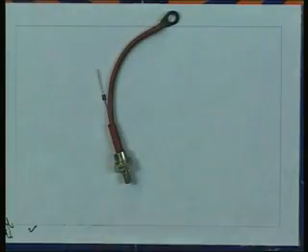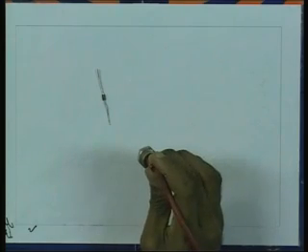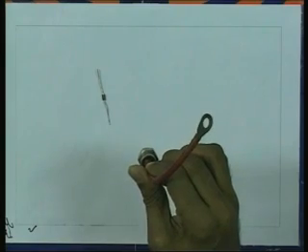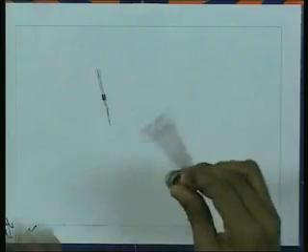High power diode can carry 40 amperes and it can withstand 1200 volts. See, if I use a diode in an AC supply, in the negative half cycle, the diode may get reverse biased, and it has to block or withstand the voltage, whatever the input voltage. So this diode can block a voltage up to 1200 volts.